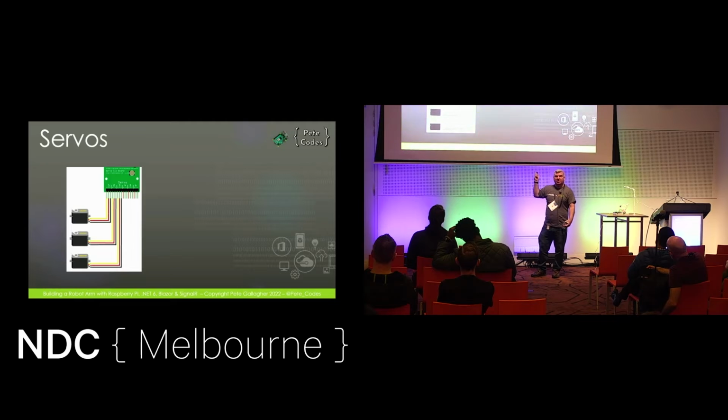And then on the other side of that Servo 6, we've got these servos. Now, these are what's called 9G servos. They're just dead cheap. You can buy them from Amazon for pennies. It kind of does mean they're not all the same, and I'll talk a little bit about that. But for the most part, the colouring of the pins on there will be pretty similar, but there might be orange and brown like I've got instead of yellow and red, but you'll figure that part out.